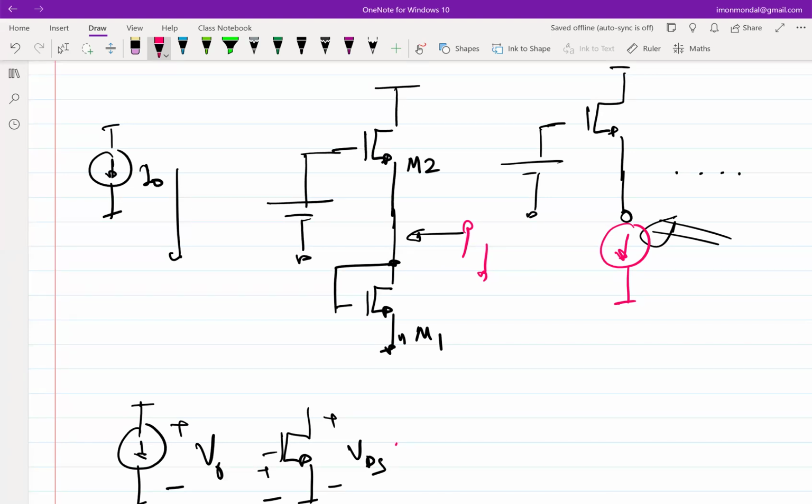Let's say the voltage increases, right? If this voltage increases, the condition of M1 is asking for more current to be sunk in. But what is the condition on M2? What is happening to M2? VGS is going to reduce, which means M2 is trying to reduce the current, right? So there is again an inherent feedback mechanism associated with this.